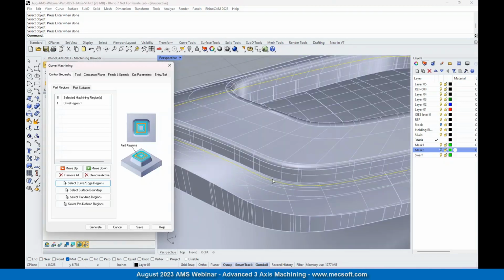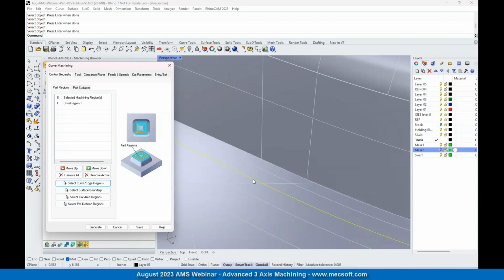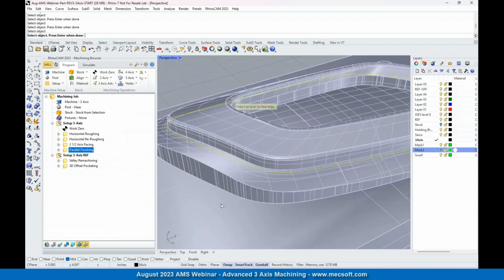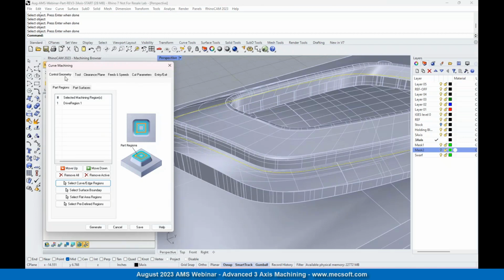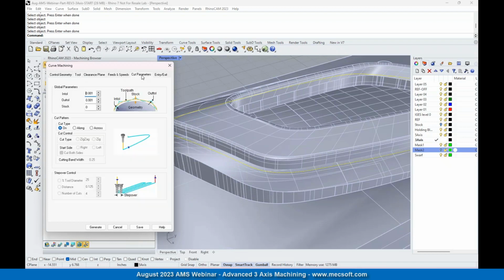Okay. And this is offset from this wall, actually. We don't want to cut this wall or touch that wall. So we're going to stay off of the wall by this amount. In fact, let's go ahead and remove that and select this other one just to make sure that we're plenty enough away from that wall. Okay, and then for the tool, we're going to use the 1/8 inch ball mill. So let's get the 1/8 inch ball mill, and we're going to go with cut parameter here.